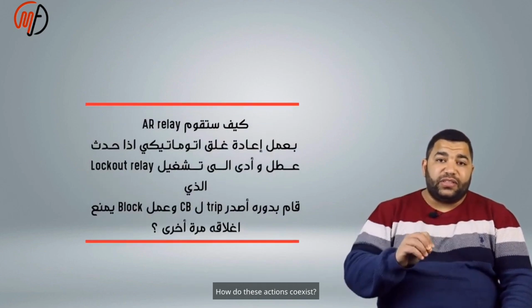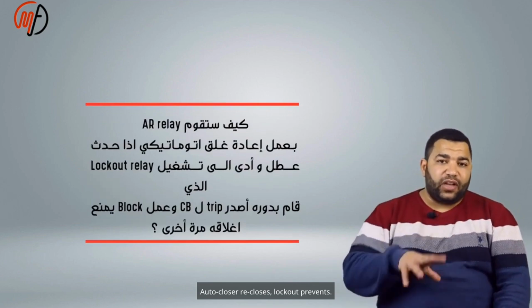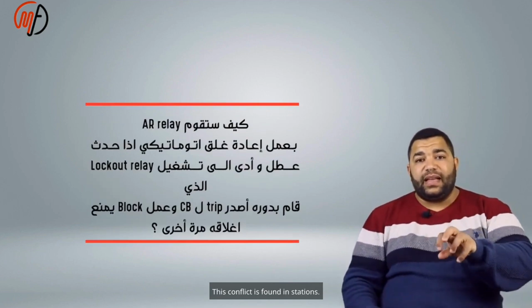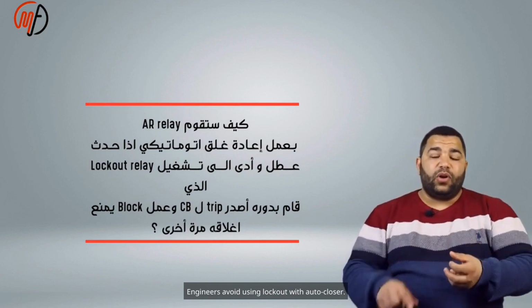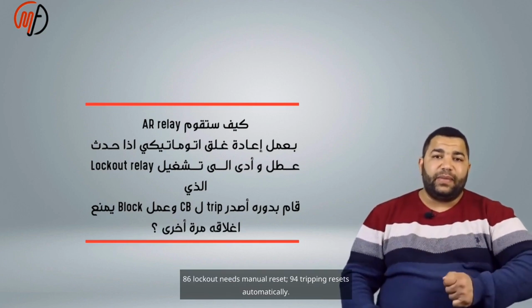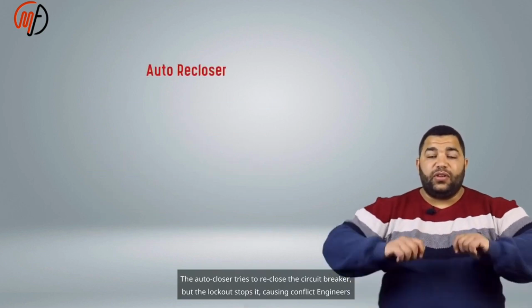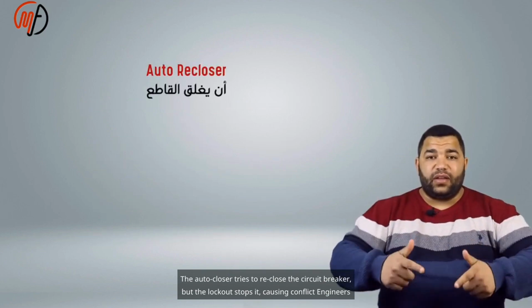Faults may cause automatic reclosing despite lockout disconnection. How do these actions coexist? Autocloser recloses, lockout prevents. This conflict is found in stations. Engineers avoid using lockout with autocloser. They use the ANSI 94 tripping relay. The 86 lockout needs manual reset, while the 94 tripping relay resets automatically. The autocloser tries to reclose the circuit breaker, but the lockout stops it, causing conflict.